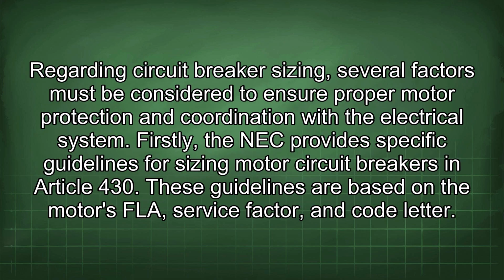Regarding circuit breaker sizing, several factors must be considered to ensure proper motor protection and coordination with the electrical system. Firstly, the NEC provides specific guidelines for sizing motor circuit breakers in Article 430. These guidelines are based on the motor's FLA, service factor, and code letter.